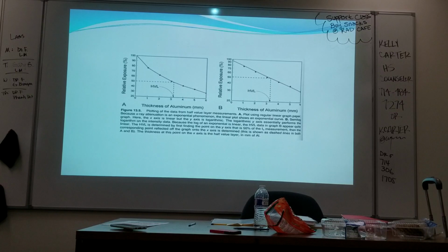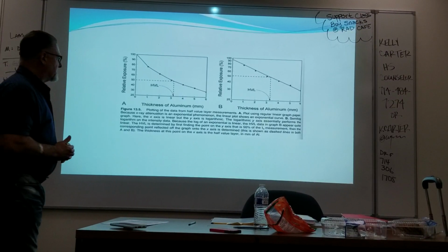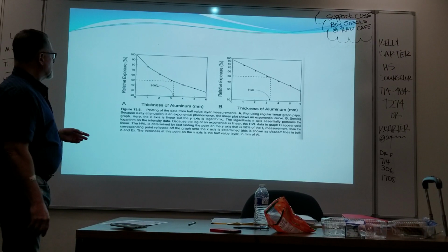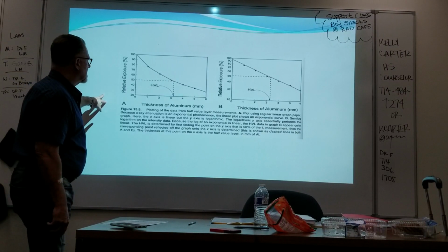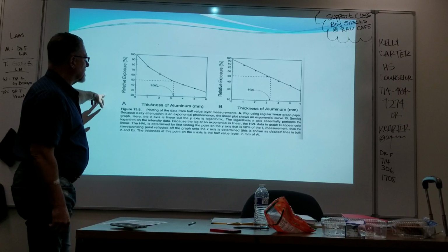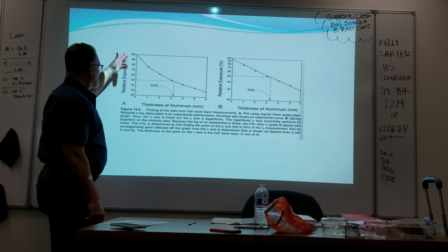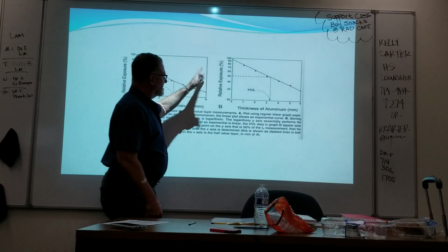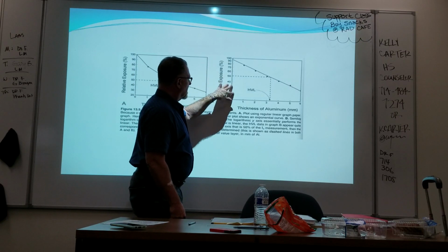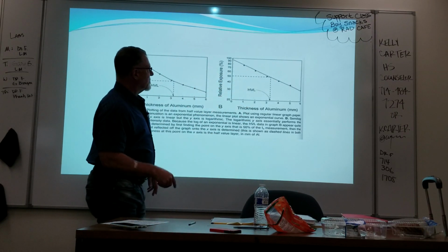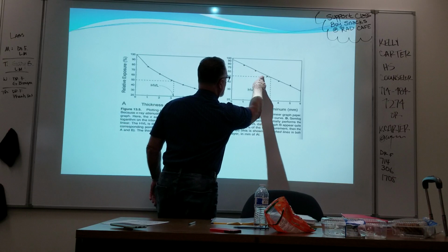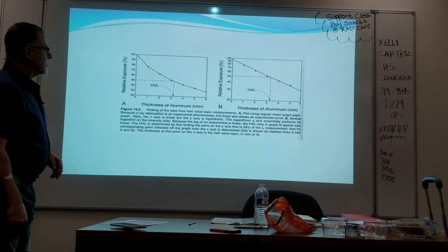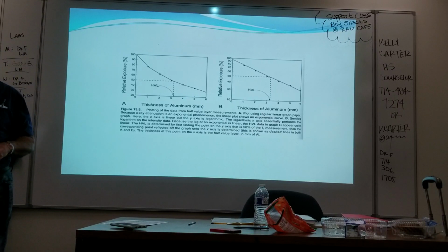Anyway, so this is a plot for HVL. So you've got relative exposure as a percent. You've got thickness. This is on a standard scale. Notice this is kind of a curve. When you put it on a log scale, you get kind of a straight line, you still get these slight differences from a straight line, and it has to do with hardening. So it's very, very minor. But that's how you would plot HVL.